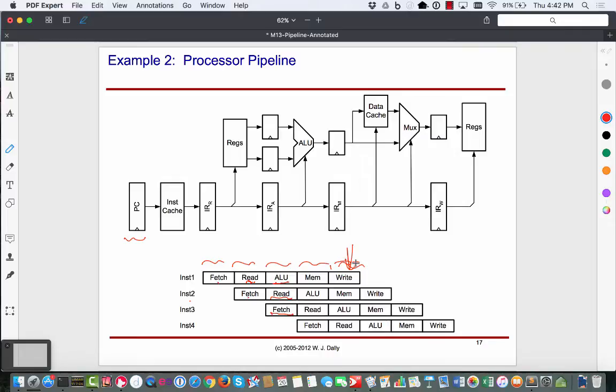Yeah, just wait. It has to stall the pipeline, right? Because I don't have the data I need. I cannot proceed further. So in essence, nothing would be done, and you can think of it as a vacuous task or a bubble which gets inserted and flows through the hardware. So hardware is idle in that case. So conditional things like if then else, for loops, while loops, anytime I have a jump of some form, potentially creates a problem for a pipeline kind of architecture. And the deeper the pipeline, the worse off you are, right?